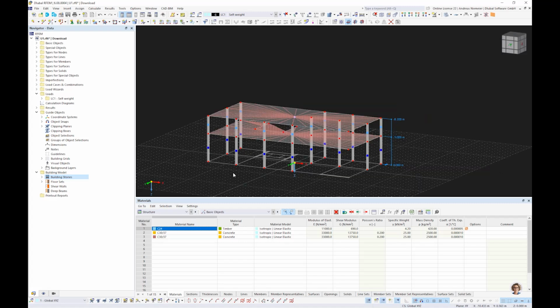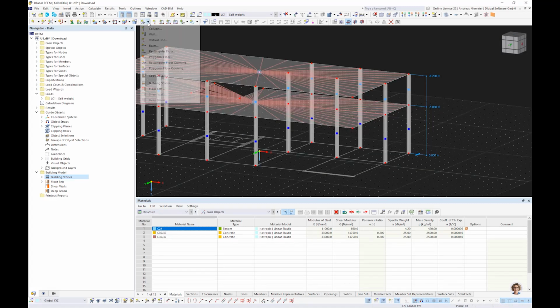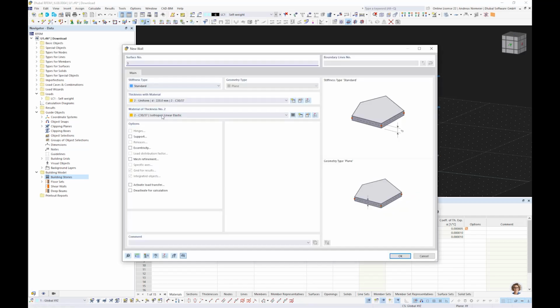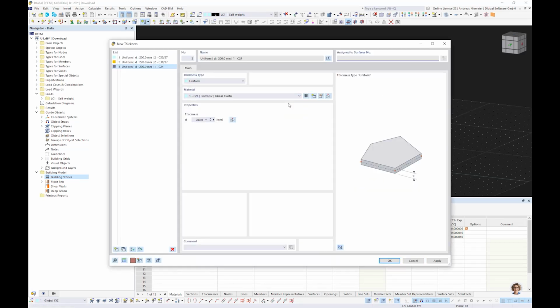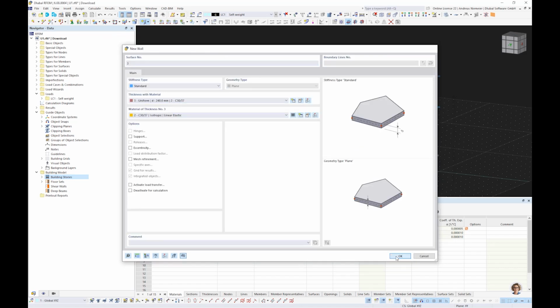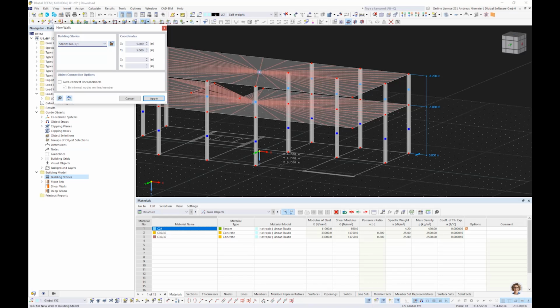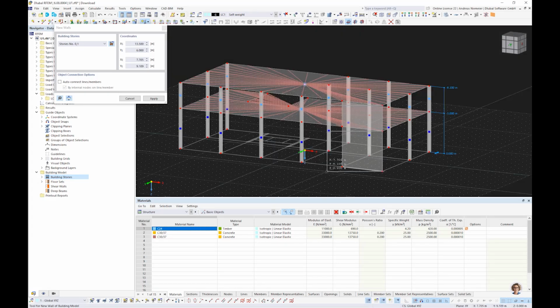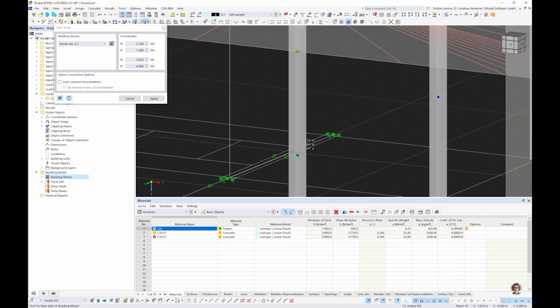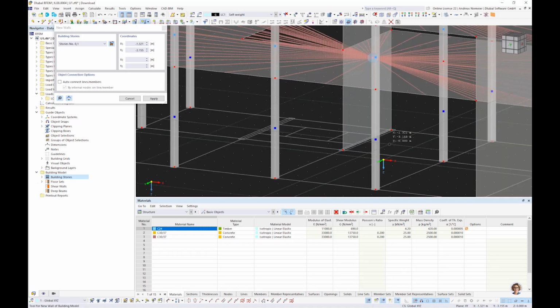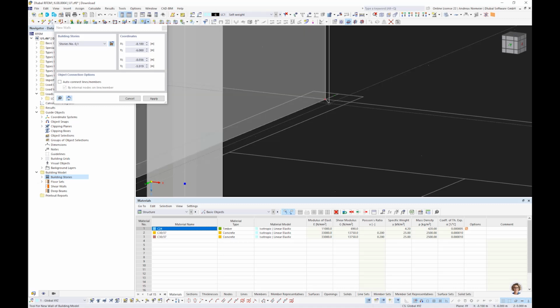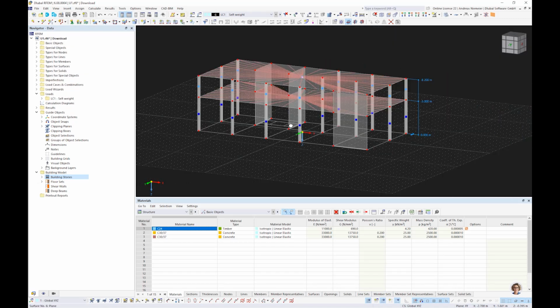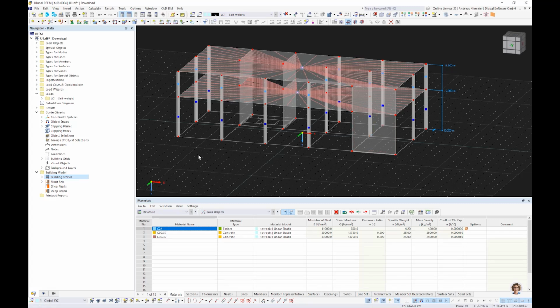And now we see we have also walls here. No problem, there is also a wall command where you can select maybe different thickness, maybe here 24 centimeters, for concrete. And if you pick it, you can say for which stories. I say for all. And now we define the wall should run from here to here, and the same for here to here, and maybe the last one from here to here. So easy it is to define a building with walls, ceilings, columns, and now it works like before.